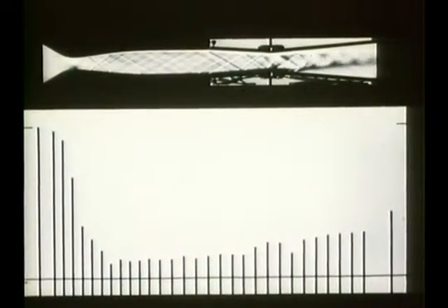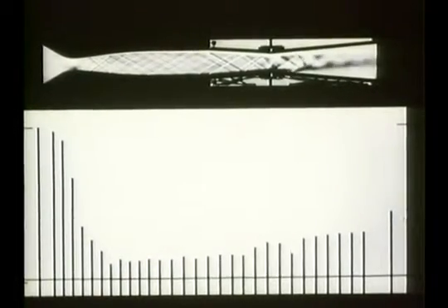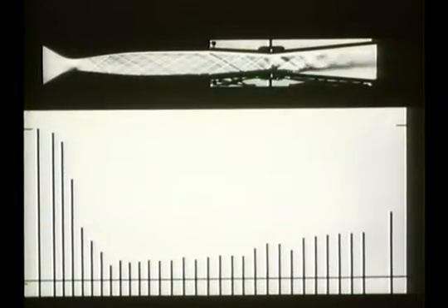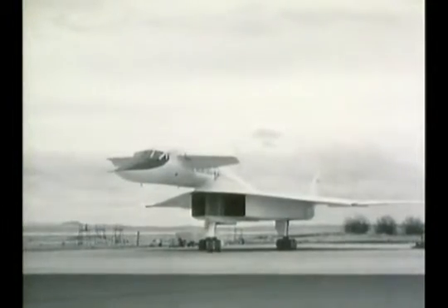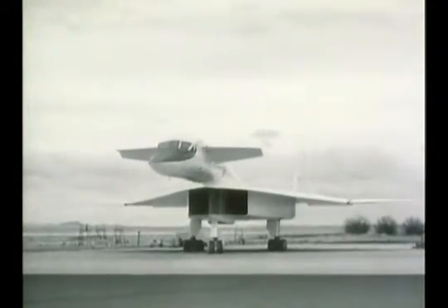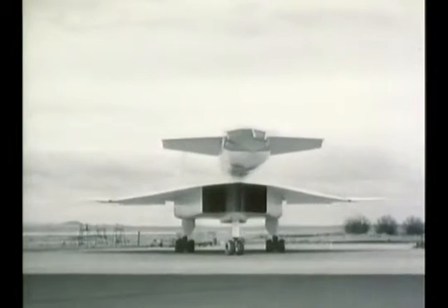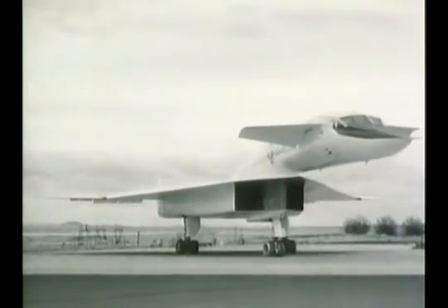The advantage of using an adjustable second throat to control the airflow is that the stagnation pressure losses and hence the power required to run the channel can be reduced below the requirement for starting. Here we are looking down the throat, so to speak, of an engine inlet designed to operate at Mach numbers up to 3.